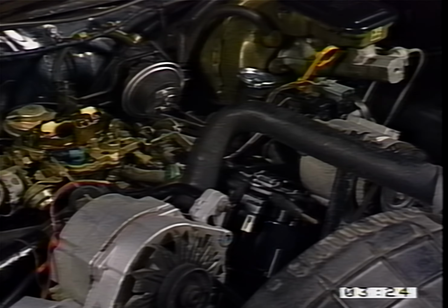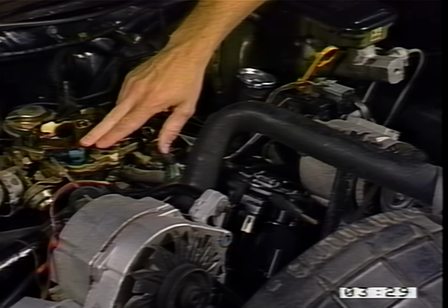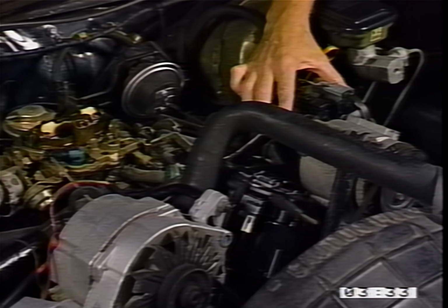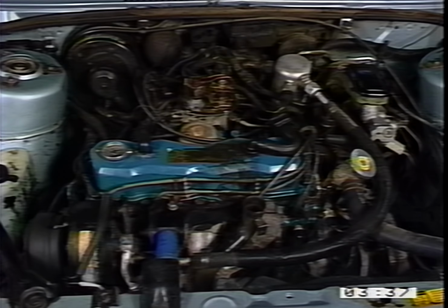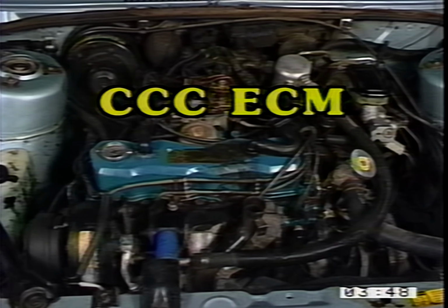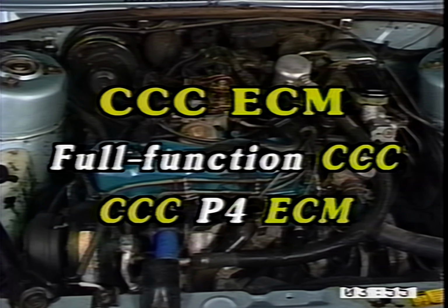Unlike its predecessors controlling only spark, C3 in most applications is designed as a full-function system controlling fuel ratio and spark advance along with a host of additional engine functions. The C3's primary design function is to improve mileage and emissions without sacrificing drivability, which is the problem of earlier spark control designs. The C3 ECM is found in two common engine control designs, the full-function C3 and the later C3P4 ECM.